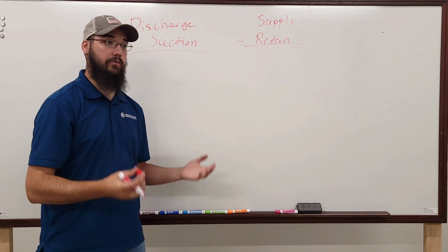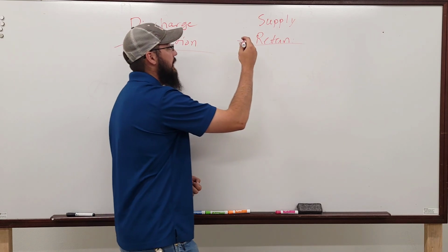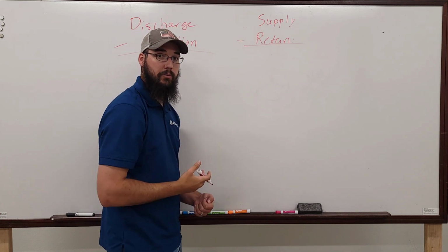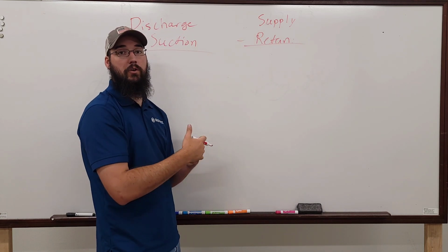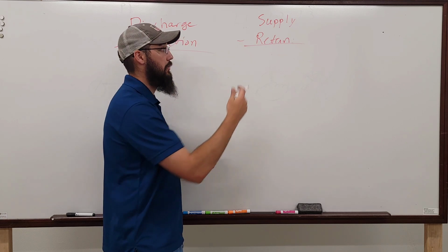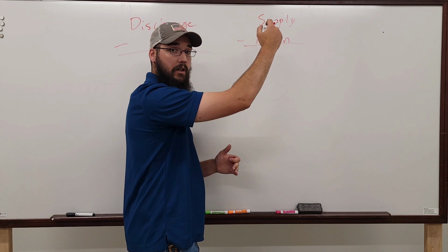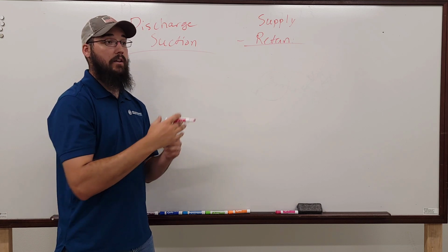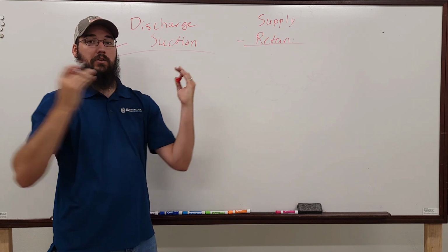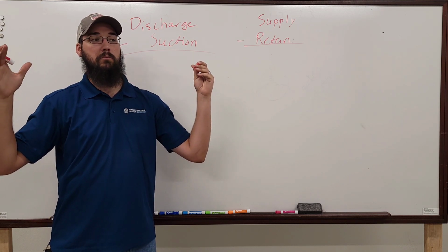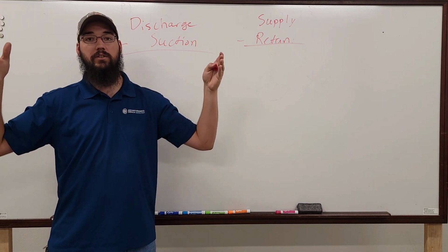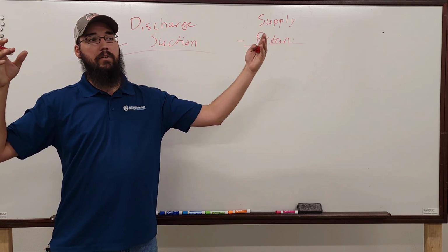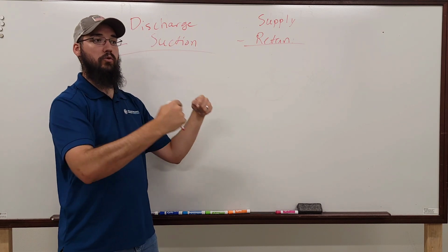It's a centrifugal force device. With that, the higher this is, the more work you're having to do. And you can get into what is known as a stall, right? Stall is where you literally get so high on this differential that the blowers just physically can't do it. You're just pushing back on it? Yeah, there's so much back pressure coming back, and so much negative behind it. You literally get to a point where the motor falls into a stall state, where it's not actually moving the amount of air. The air literally gets trapped in the louvers.